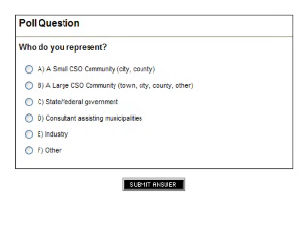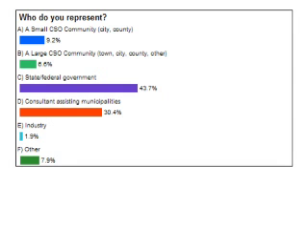That means, if I understand you correctly, that means Atlanta is demonstrating if they can achieve the maximum 4 overflow, they can achieve the water quality standard into receiving water. No, that is not a requirement. That was just a general requirement to design the system, but that's not part of the permit requirement. They are basically treating all of the flow. They're even disinfecting those residual overflows, those 4 overflows per year that don't get into the tunnel and treatment system.